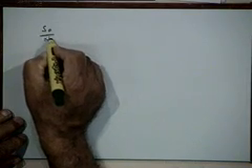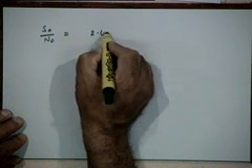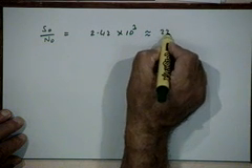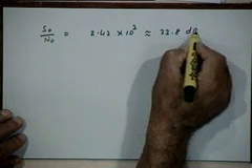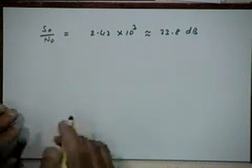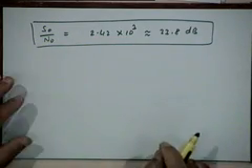And if you were to now calculate the signal to noise power ratio, that turns out to be 2.42 into 10 to the power 3, which is of the order of 33.8 decibels. So I thought we will go through one sample calculation to get this idea of how you actually calculate the signal to noise ratio and what is the order of values that you can expect.